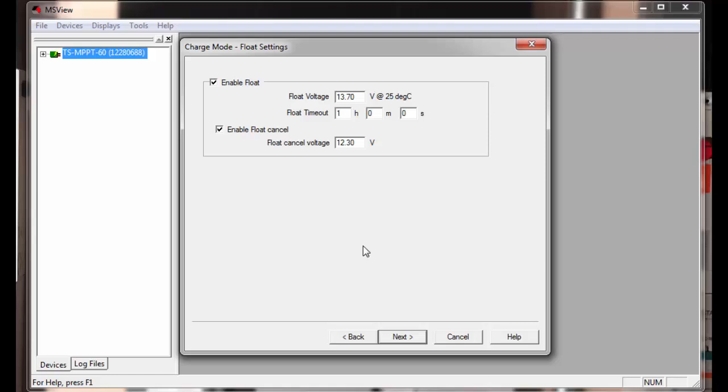So I've heard of some battery manufacturers suggesting higher settings for the winter. The additional strain on the batteries can justify this in the shorter days, so you don't really have to worry about extended periods of it being in float, and it gives you a little bit extra charge if it needs it. So 13.8 should be fine, and this is the kind of setting that you can adjust if you find it useful. I mean, generally our settings should be pretty good. And if you need to bump them up or lower them a little bit, you're free to do that however you wish.